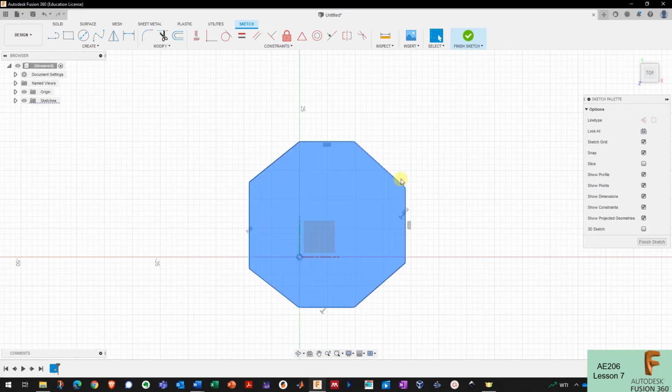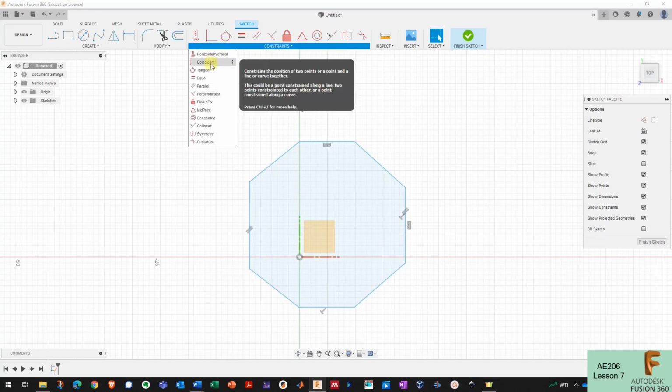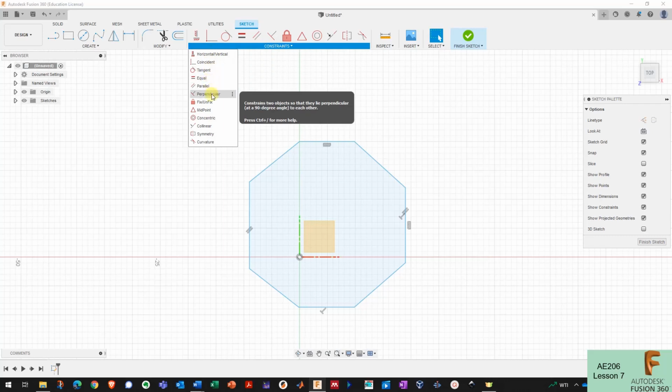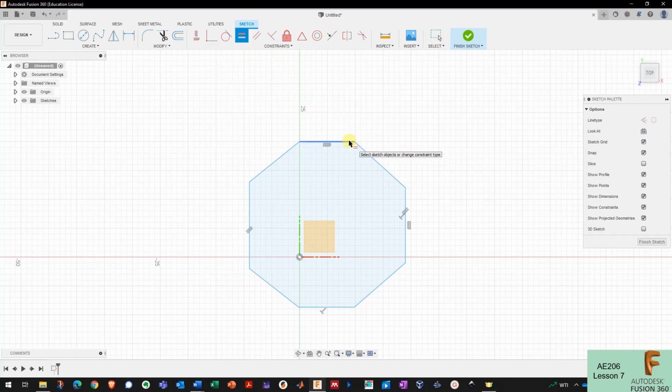So that can be a really useful trick for you to figure out why your sketch isn't closed. But anyway, I have a closed sketch here now, and it looks kind of octagonish, but obviously these sides are not equal length right now, and they may not be parallel to each other either. So I really need a way to enforce some conditions on these lines, like equal length or parallel, etc. And the way we do that is through constraints. Here's the constraints menu up here. Here's all the types of constraints that I can apply to sketches, lines, and points. The ones I'm interested in right now are equal and parallel. So I'm going to click on the equal constraint and click on the first line and the second line, and the two lines become equal length.